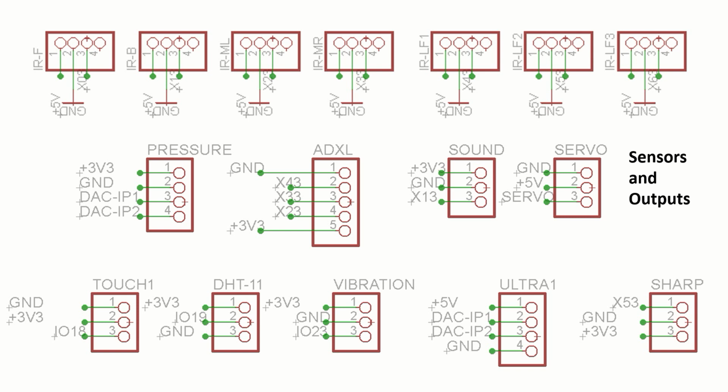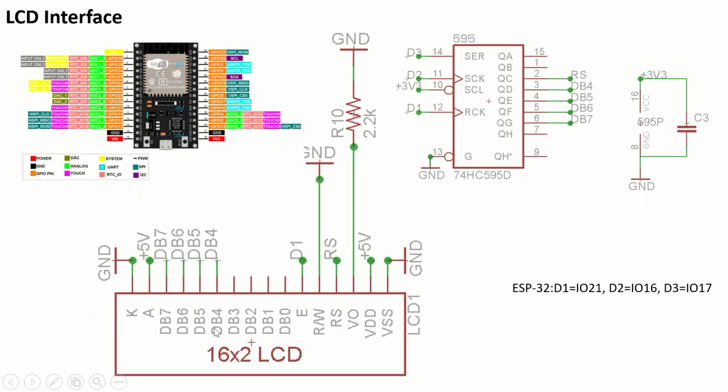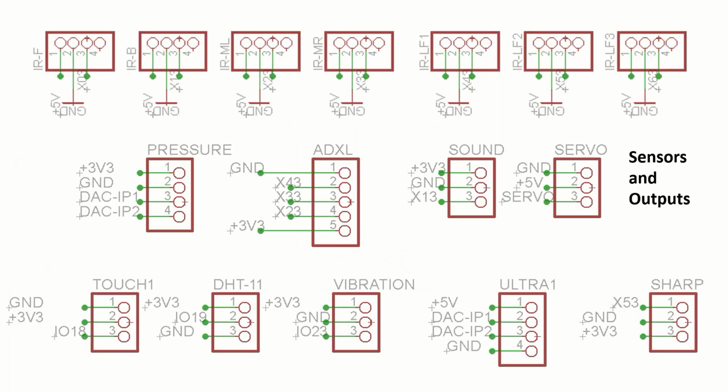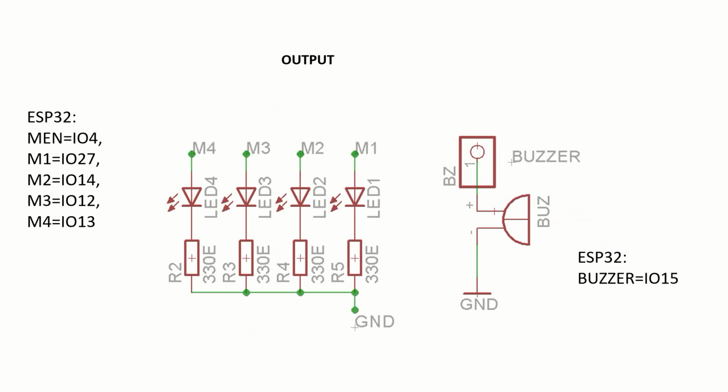So what will happen? Your microcontroller will receive 3.3 volts on IO19, and it will try to read that pin and display it on some LED or some serial port. LED is very simple: read the IO19 pin and output the same value where the LEDs are connected.